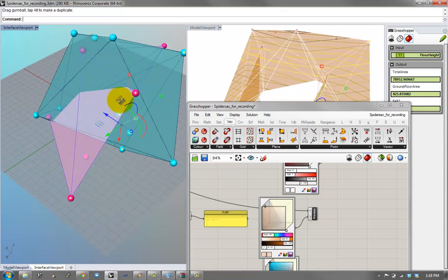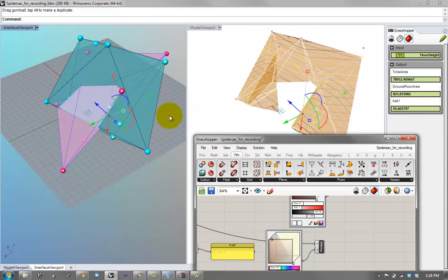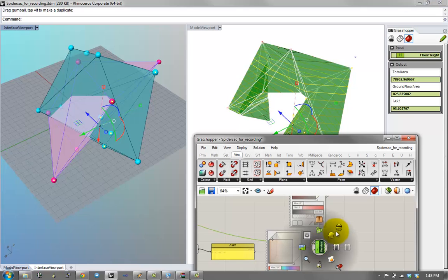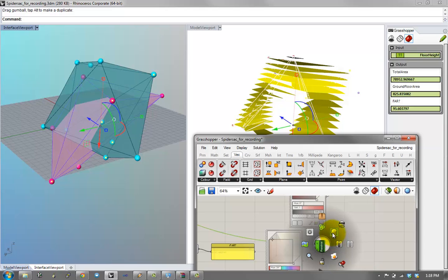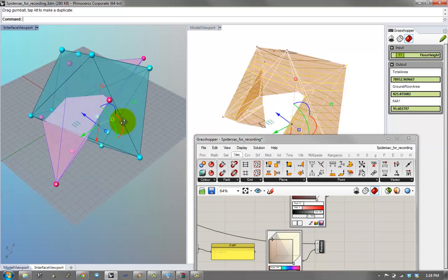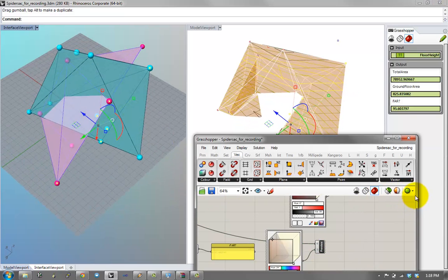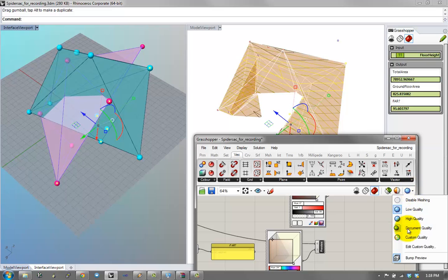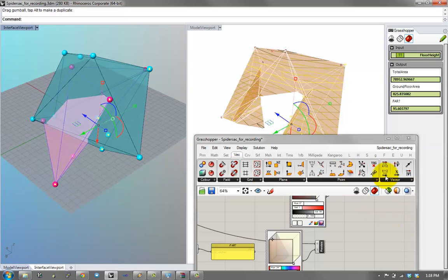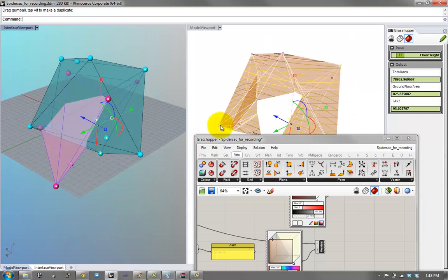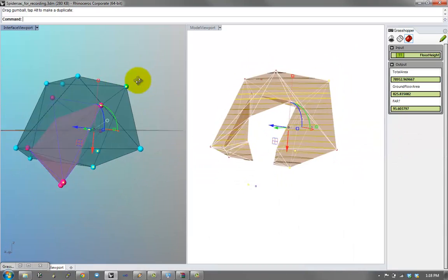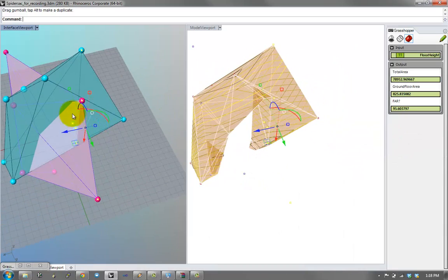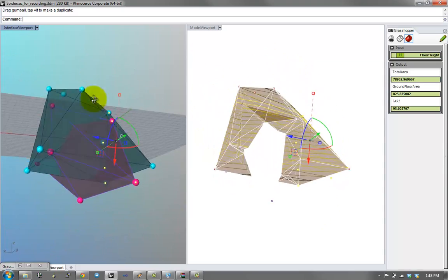One thing to note, the one downside to Grasshopper is that if I hide this object, you'll notice that you can see the floor plates. If I show this, even though I have a transparency on, the transparency doesn't often work that well, even if you go to, say, document quality. That's just something you have to work around. So this is great. Now I'm seeing the coloration of the floors.